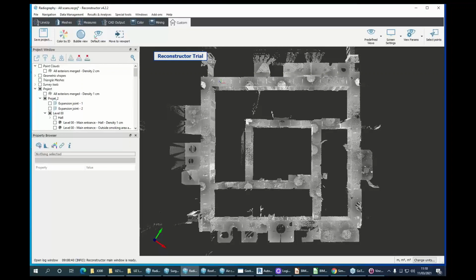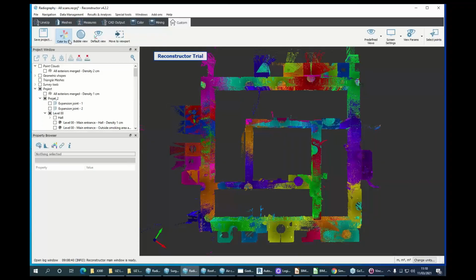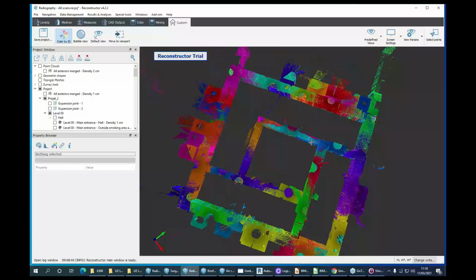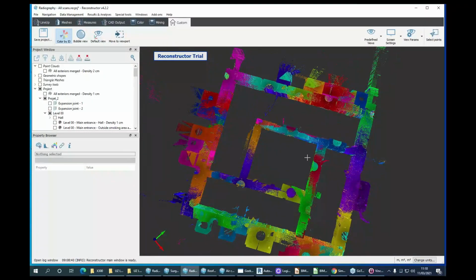We were just there. When we were doing the first two scans, we were at this location and this location. This place is actually one of the most difficult places we had to scan in that building and in most of the projects because everything is in a straight line, as you can see. So if there is any kind of deviation or any kind of registration error, everything will not match, and at the end, the corridors or the floor will not match together. That's actually not simple, and it was a bit difficult for us to process that correctly. We did some additional scanning after that to make sure that everything was fine.